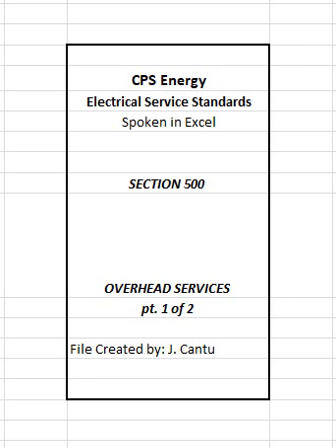506.1 Location. Service raceways shall be installed on the outside of the building or structure and be continuous except for couplings. Couplings or fittings shall be listed and provide no access to unmetered conductors, refer to definition of listed.